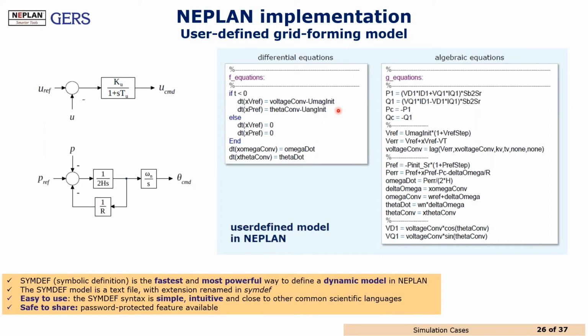For example, the grid forming inverter that we are going to model here is based on the virtual synchronous machine specification. This is a virtual synchronous machine control. And what we have here is the definition of differential equations. We have a text-based file, which is able to create the specific model for the differential equations and for the algebraic equations. These equations can be included here in the user-defined model.